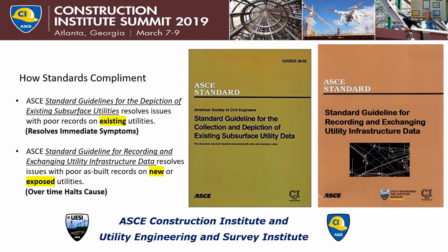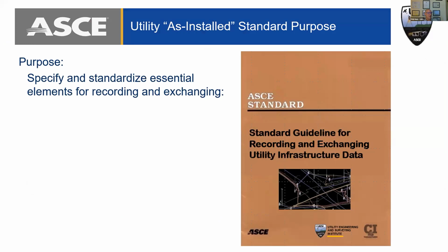collect this data so we can basically have it in a format that can flow into augmented reality and Navisworks and other uses? Because right now the ASCE 38 standard was focused more on a drawing type of format, and what we want is digital data that's in a useful format. So we didn't try to define a data schema. We just wanted to define the raw data elements and how to collect that data so that it can flow into these applications. And basically, we outlined a framework for a GIS system to manage this data.